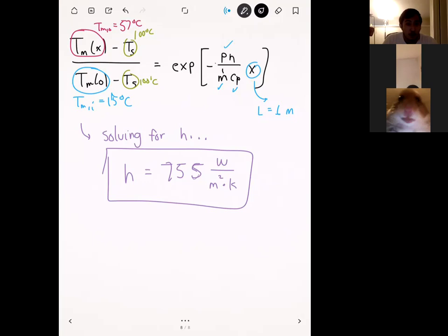But what happens when we have turbulence? We've kind of been sidestepping that issue a little bit in these lecture notes. It turns out there is a Reynolds number correlation for internal turbulent flow. Unfortunately, it's not as simple as the laminar case. If you do want to solve for the convection coefficient with the Reynolds number, and you have turbulent flow, this is basically the expression that you use.